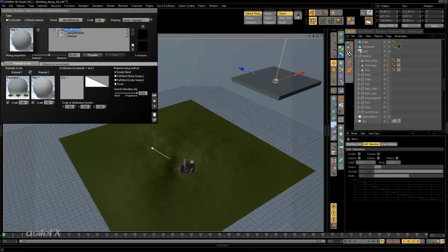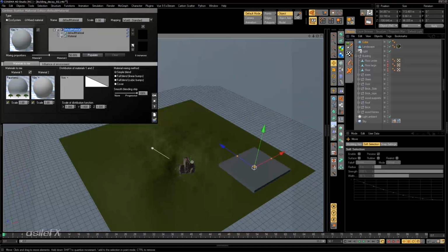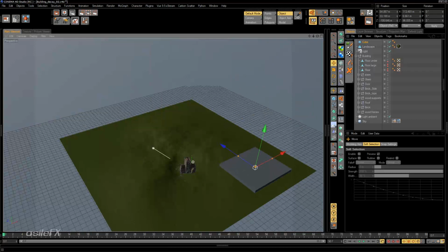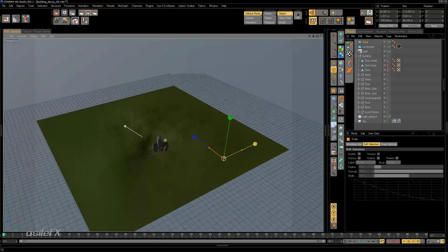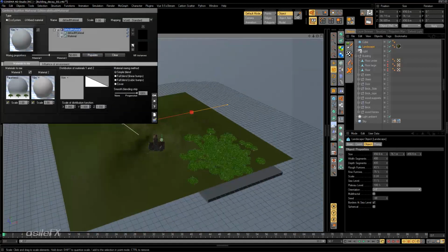If we go ahead and select this object, and we may need to close it out in order to get that to refresh. And now it's showing properly. So since the function is 3D, it's basically a sphere. It's not two-dimensional. It is a sphere that is showing up with a full gradient. So obviously if we move it too high on the Z, we're no longer going to see that sphere because it's going to move too far out of the way.